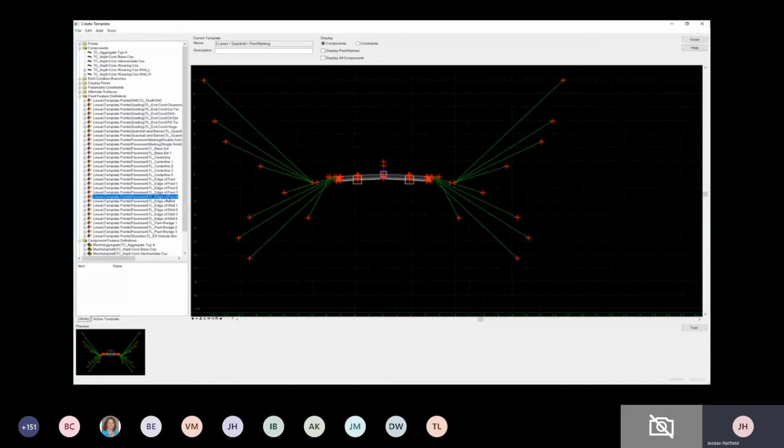Edge of pavements, level 4, pavement 4 being the fourth point down, 3, 2, 1. These are all separated in this way so that these points could be isolated to create different graphical filters to pull in different types of surfaces that you might need in construction to represent each course of pavement or the rough grade or any other variety of situations that you may need.